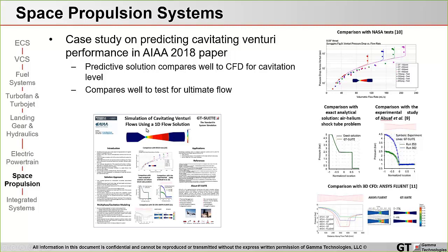Now, the venturi can be done in a predictive fashion like this, and you can see there's good agreement between GT and 3D CFD models out there, so, for example, with ANSYS Fluent. But we've also compared this predictive approach to test data that's available for a variety of different upstream pressures and so forth to give a truly predictive solution. But the user can also, for a system level modeling approach, characterize it in a non-predictive manner as well.